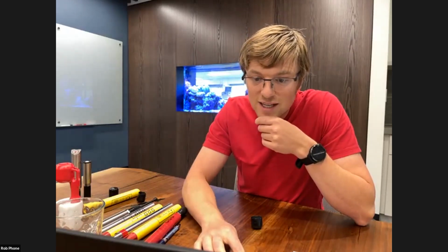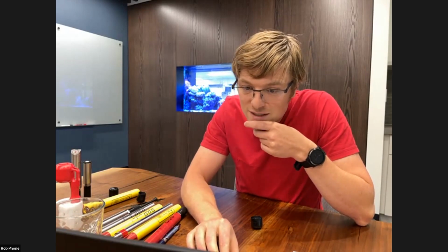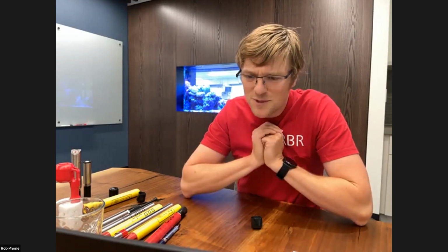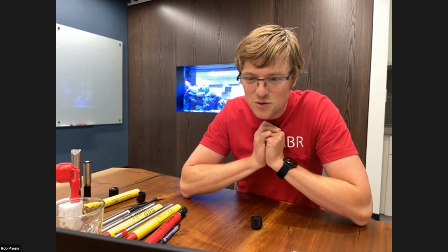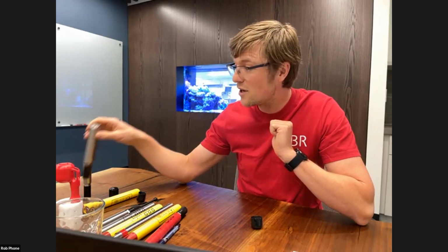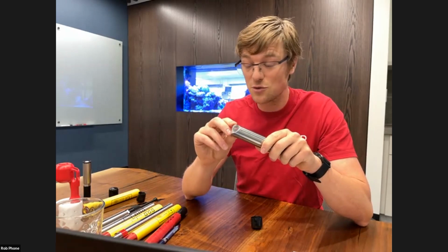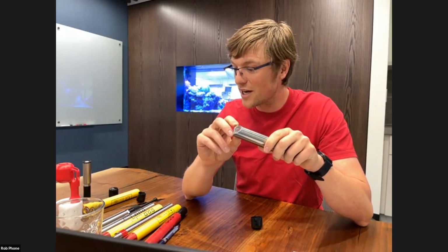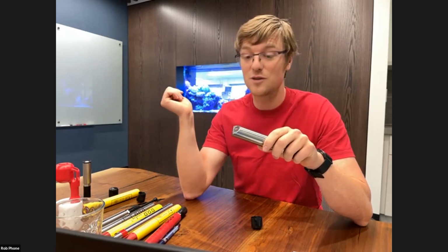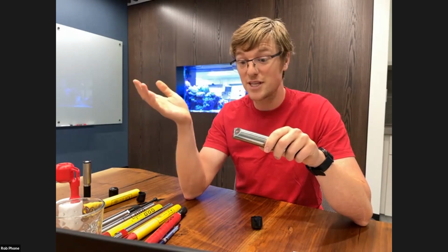So Xiaodong asks, I see you have radiance sensors. Any plan to make radiance sensors? Oh, I'm sorry, I'll have to follow up with you on that one. I'm not too sure what you mean there. Yes, and Frey asks, what influence has depth pressure on other sensors? So it's a great question. So the oxygen foil on the dissolved oxygen sensor has a sensitivity to pressure. They've been characterized both at sea as well as in our pressure chamber. They have an effect of about 3% per 1,000 decibars.